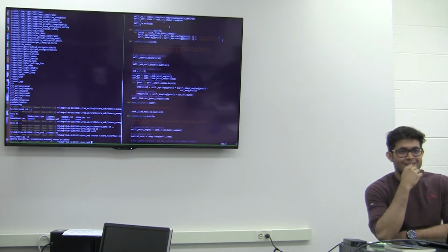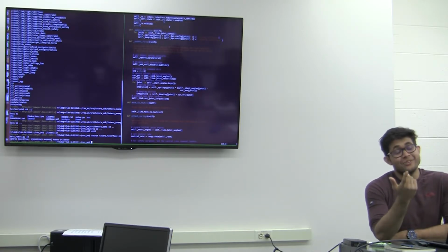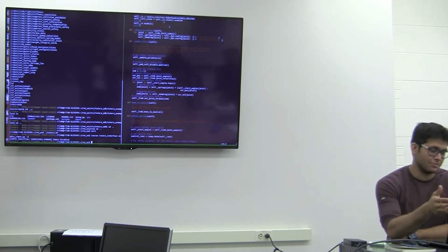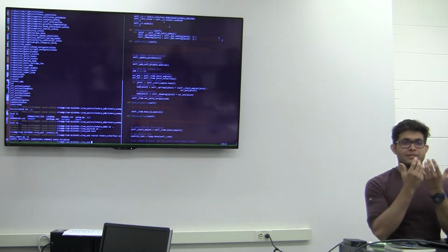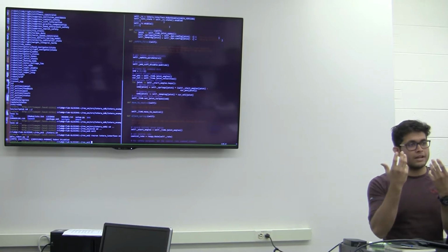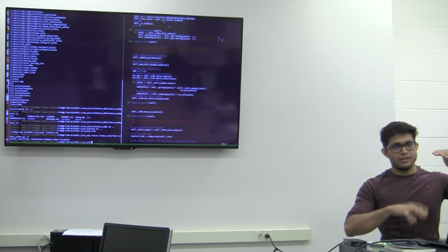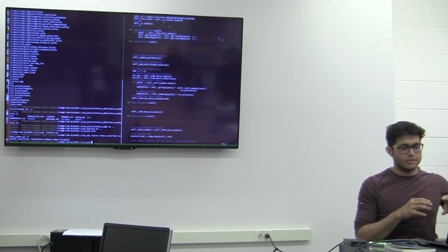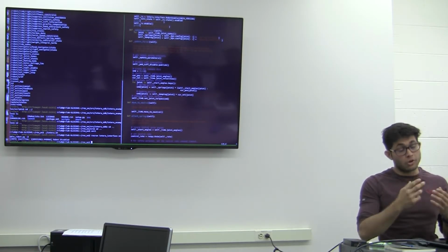If we're adding a component, for example a camera above the wrist, and we want it to be in the URDF, you don't actually change the URDF. You add another one. That's how macro comes into the picture. Macro allows you to add two URDFs. You just create another macro file and create a pseudo link. This is your camera URDF that you got from an open source platform. This is your robot URDF that you got from an open source platform. You create a pseudo joint that links both of them.